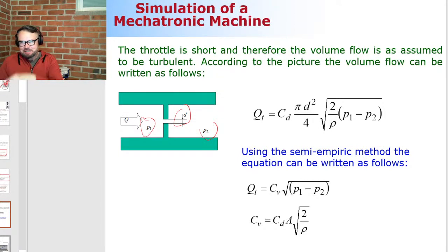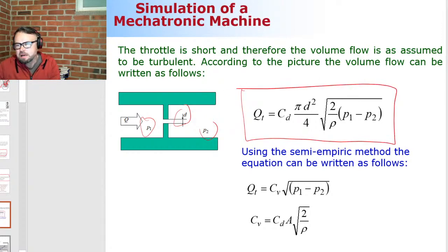All right, so back to this throttle valve. The throttle valve analytical equation can be computed like this. I have here the pressure difference under the square root. Then I have the diameter of this throttle and the discharge coefficient, which you can easily get from pre-calculated tables. But still, getting this diameter from the throttle valve, which physically looks like just a chunk of steel, and measuring it somewhere deep inside of this component may be quite a challenge.